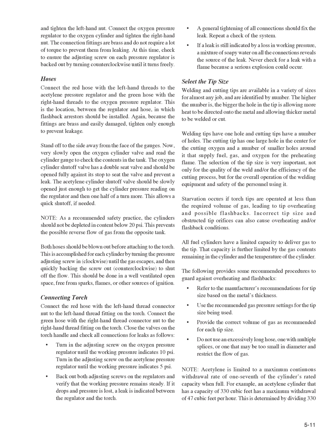The selection of the tip size is very important, not only for the quality of the weld and/or the efficiency of the cutting process, but for the overall operation of the welding equipment and safety of the personnel using it. Starvation occurs if torch tips are operated at less than the required volume of gas, leading to tip overheating and possible flashbacks. Incorrect tip size and obstructed tip orifices can also cause overheating and/or flashback conditions. All fuel cylinders have a limited capacity to deliver gas to the tip. That capacity is further limited by the gas contents remaining in the cylinder and the temperature of the cylinder.